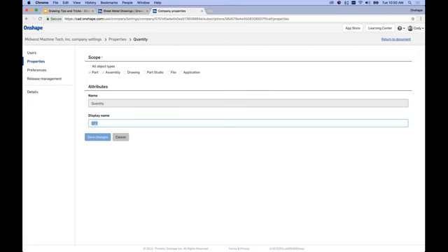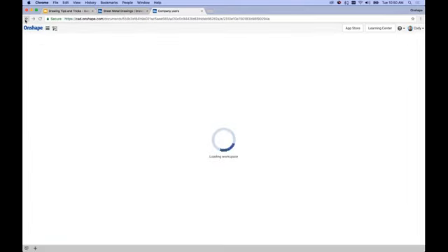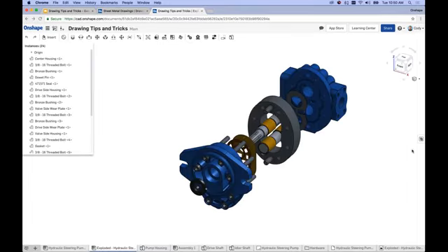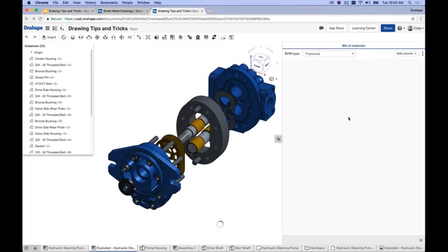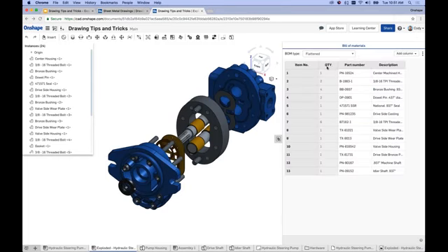So essentially, think of any scenario where you have part number as a property, but you want to display it differently in the drawings for simplification most of the time. Most of the time, this is really about just getting the bill of materials to be as narrow as possible, to take up as little width as possible. All right, so that is changing the display name of individual properties, right? Again, the reason you do that is so that when you go to your bill of materials, it's displayed cleanly. You can see I have QTY displayed as the column header here.